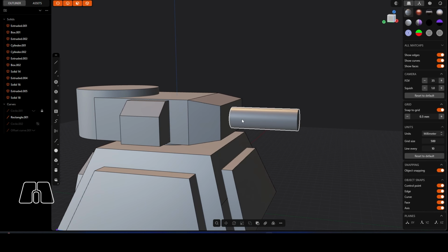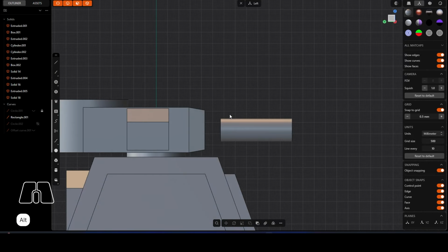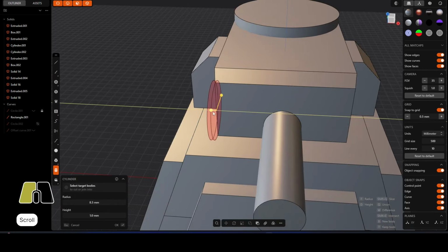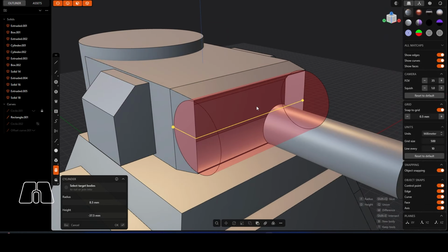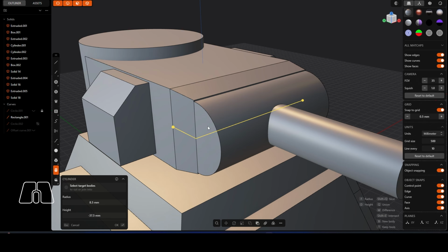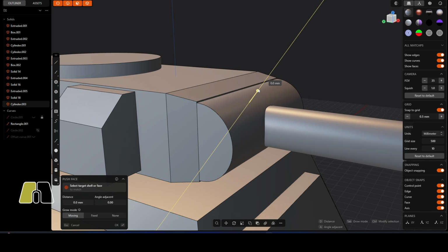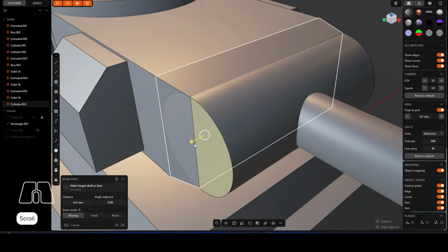So for the hinge joint, what it might be best is to actually use this sort of feature here, okay? And what we can do is, again, we'll just use a cylinder. Let's just drag out from sort of here maybe, and then we can bring this across like so. So it's going to be something like this, all right? And what we'll do is, I'm going to use the B key so it's not attached there. I'm going to click OK, and I can just see it's a little bit off from that top there. You can sort of see that where it's not quite getting what I want. So let's turn down the snap settings and just see if I can get that sort of lined up correctly. Seems okay there.